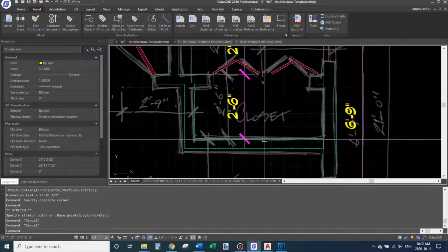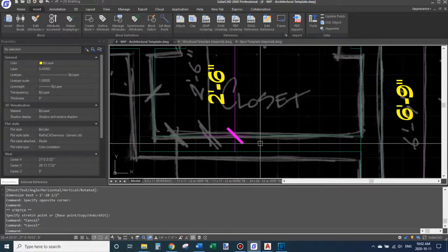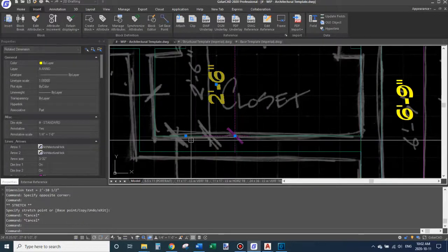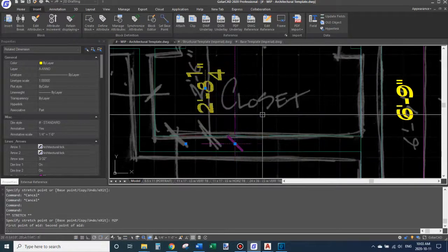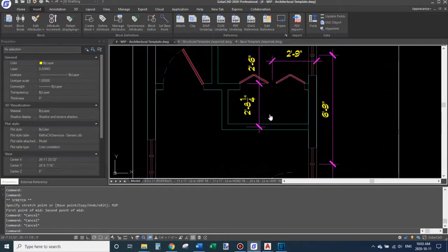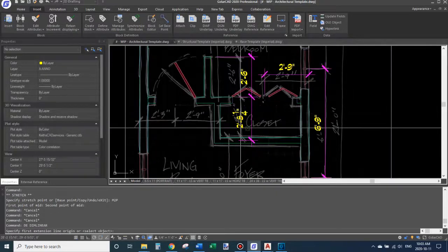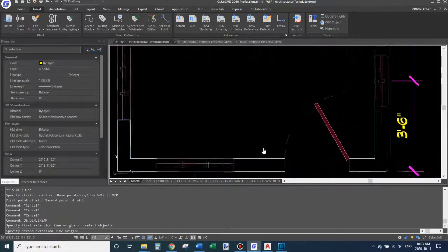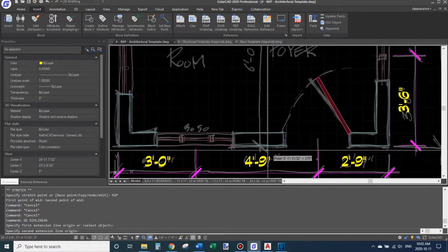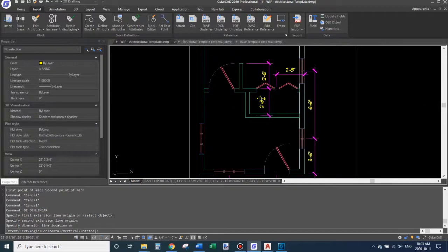And just a reminder, I think it's more standard practice to take these dimensions to the center of the wall instead of the edges. It's less arbitrary, and the reason for that is the finishes can affect where those dimensions land. Okay, let's put that guy there.